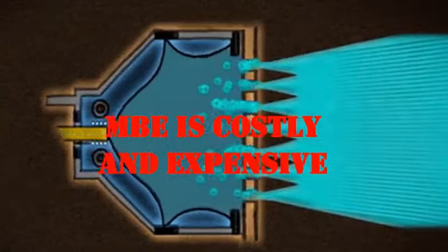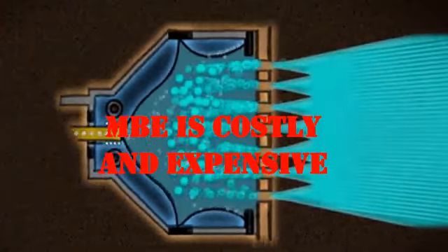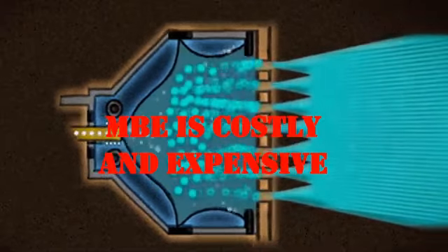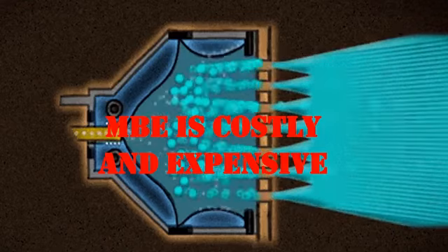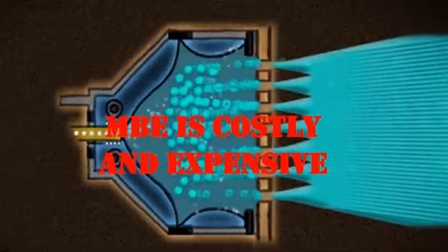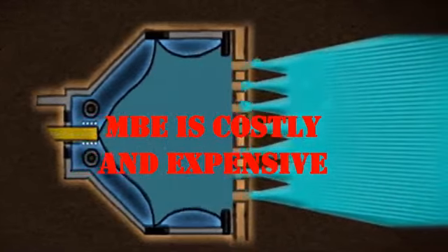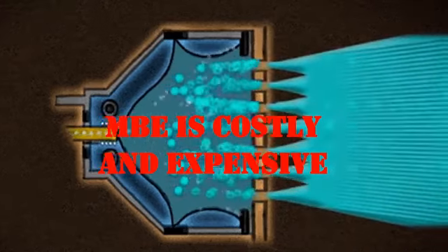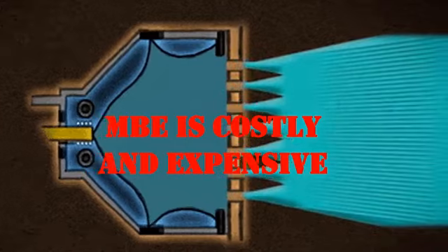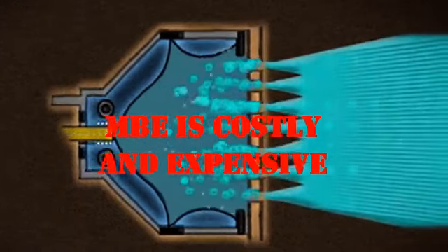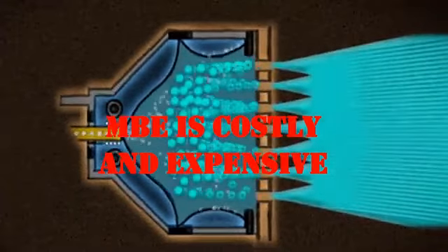The ultra high vacuum used in molecular beam epitaxy is somewhere around 10 raised to power minus 8 to 10 raised to power minus 10 torr, and for the creation of this ultra high vacuum, different combinations of high vacuum pumps are required, due to which the cost of molecular beam epitaxy becomes too much among all the other available techniques.